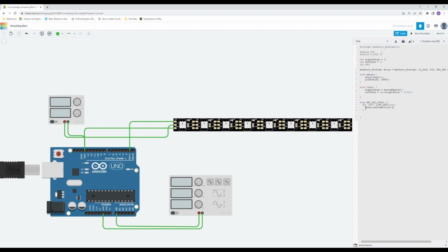What pixel are we going to set? We're going to set pixel i to the color strip.Color(0, 0, 0). So this is actually closed. There is no color going through it. So with this, we go through all the LEDs, and then we're setting everything to 0, 0, 0. Great. Next, let us create another for loop to turn on only the number of LEDs that we want.